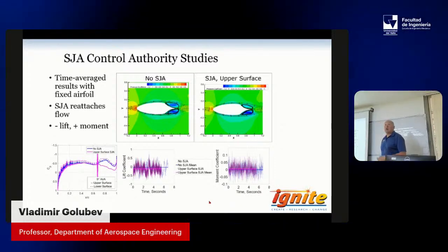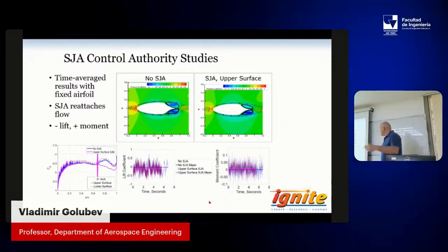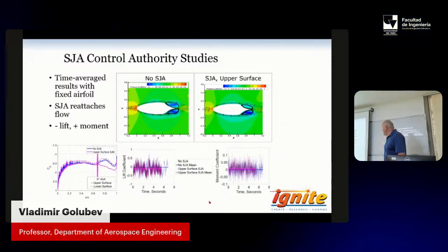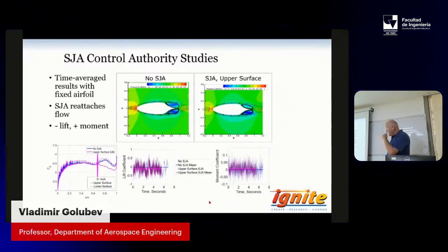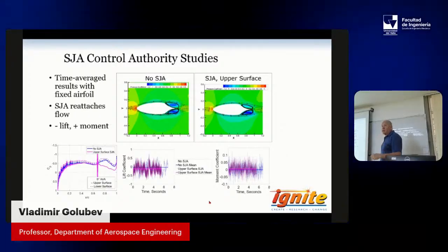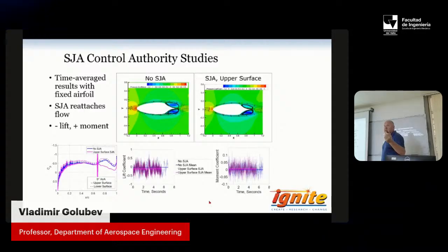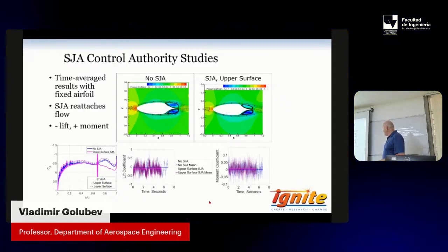And this change in pressure, that's the one which produces the moment. See, that's the whole sequence of steps here. Of course, everything is pretty chaotic in terms of the overall heat coefficient, which goes all over the place. There's a lot of shedding frequencies there, et cetera. So it's not like a steady line in reality. Of course, everything gets averaged in the end. But in real life, everything is all over the place, right?